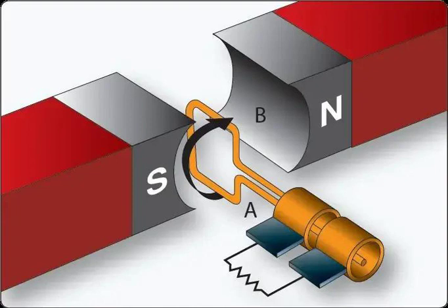Working principle. When the rotor of the DC generator rotates, the coil on it cuts through the magnetic field produced by the stator's permanent magnet or electromagnet. As a result, an EMF is induced in the coil according to Faraday's law of electromagnetic induction.